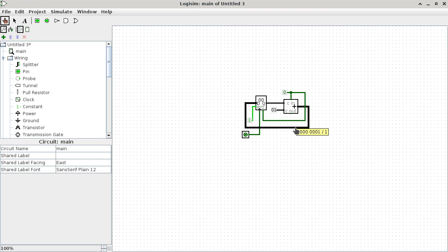Not too surprising. But what this means is the new value of the register is already presented at the D port of the register. It's not updating only because we do not have a rising edge yet. Is that okay? Everything is already set up. We're just waiting for a rising edge to update the register to 0, 1.